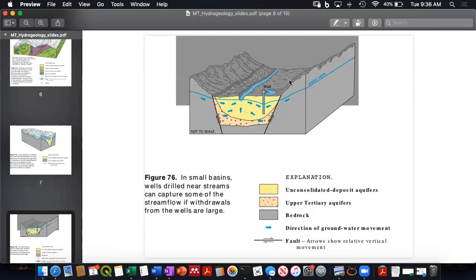We want to know things about general sources of recharge and discharge to these systems. So here is this conceptual groundwater table, which shows areas or ways that water enters the groundwater systems and exits them. The other thing that should be in a conceptual model is what are the major aquifers and aquifer types in the area, right? So this sort of shows these quaternary alluvium unconsolidated deposit aquifers and adjacent mountain block aquifer systems.